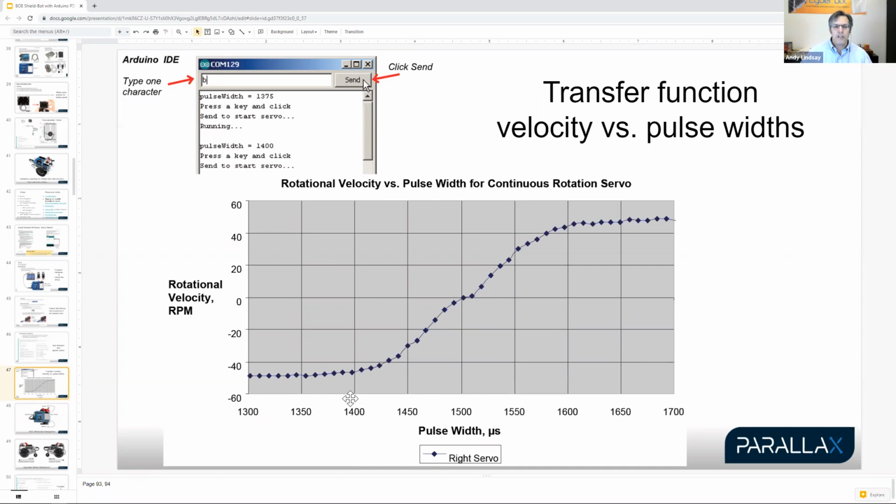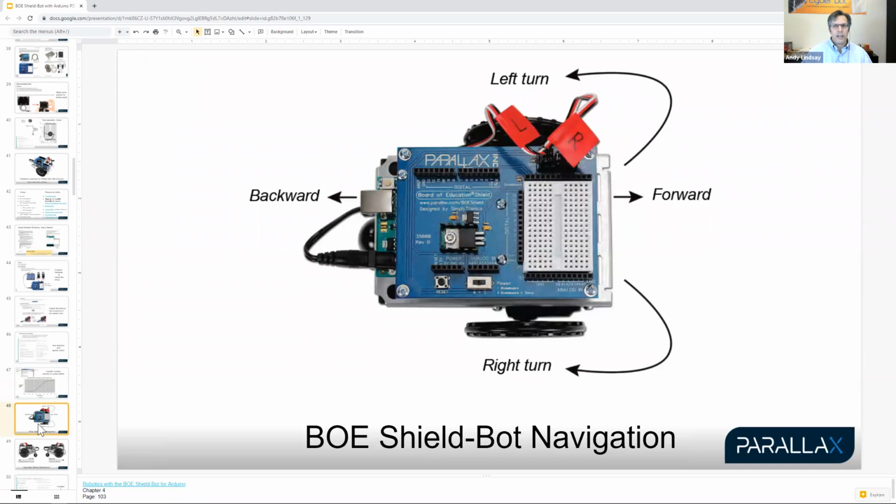So a tip you can give your students, if you think they're ready for it, depending on the grade level, is to show them this graph and explain that 1400 to 1600 is your speed control range. If you want to start slowing something down, start at, say, 1410 or 1590, and that way you'll slow your servo down. So that is yesterday in a nutshell.